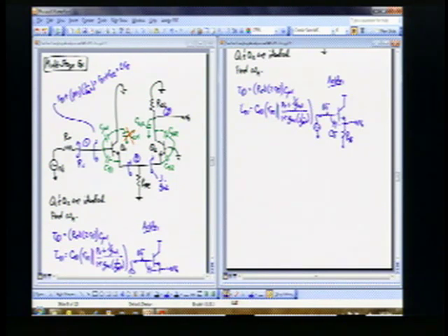So here's something to consider. A capacitor is not really there if it has no voltage change across it. And this circuit is actually the circuit for a follower, right? Which means if I have some voltage on this node, these two are going to be about equal, which means I'm not really having any variation across this capacitor.